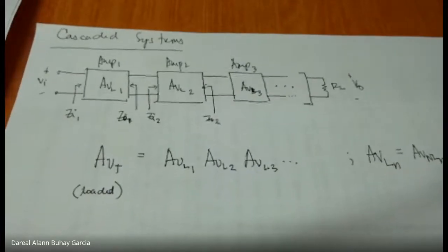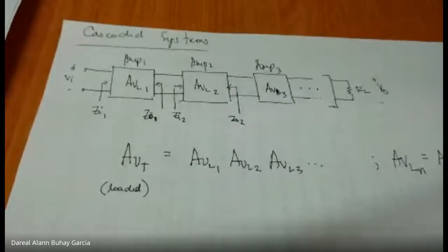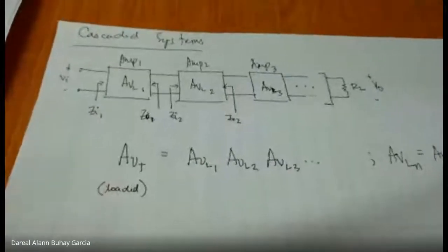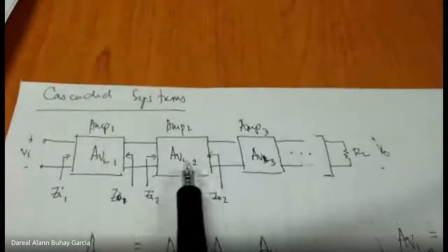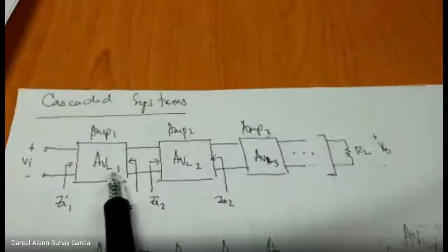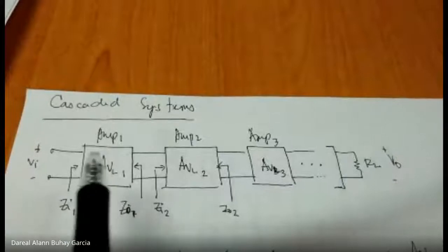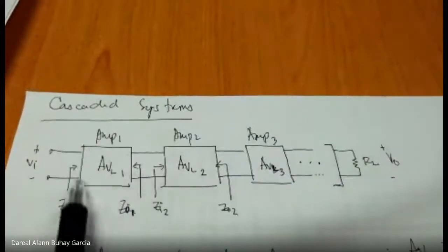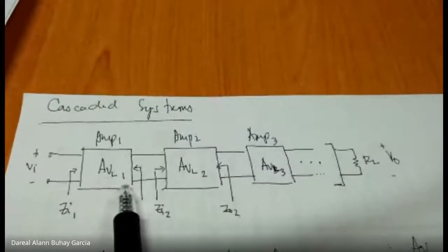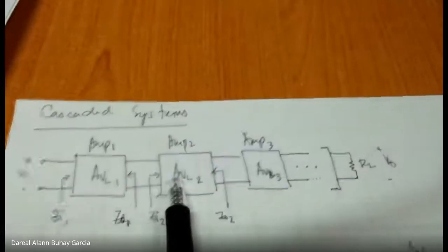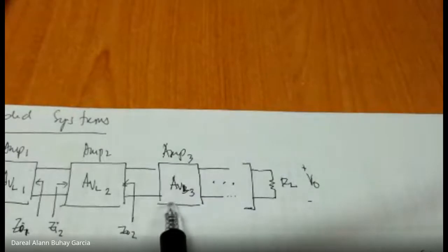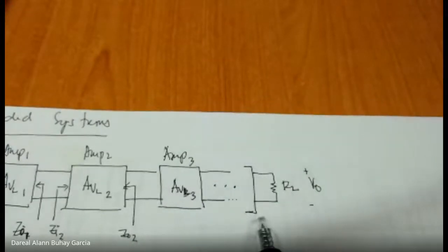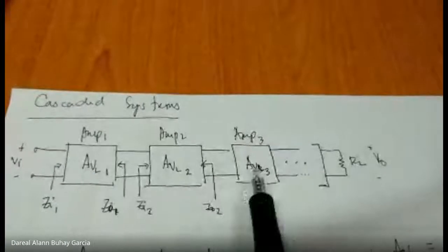So yeah, that's correct. The first stage is a low noise amplifier. Okay? Balik na dire. The given voltage gains are loaded voltage gains, because from the perspective of the first stage, its load is the second stage, no? Only the last stage of the amplifier has the actual load as its load. Especially if it's a 3-stage amplifier.